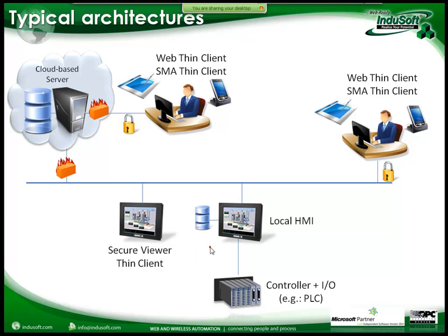In some cases, instead of having InduSoft on each one of the sites, you can configure InduSoft Web Studio running on the cloud to read data directly from the sensors, from the controllers on each one of the sites. It works just fine, and this server can work as a portal, as a web portal for remote thin clients, web thin clients.